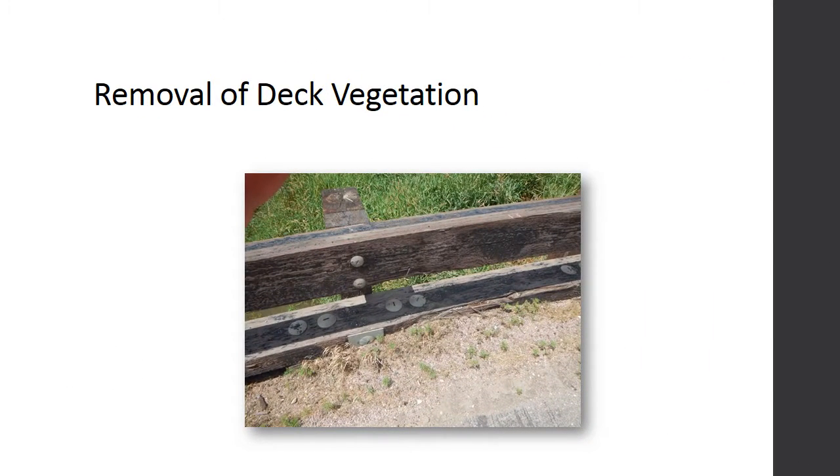Timber decks can be susceptible to vegetation growth as gaps between deck boards are quite common. These gaps fill with dirt and gravel that in turn create an environment in which vegetation can begin to grow. Vegetation growth is a clear indicator that debris has collected and water is being retained within the gaps. As such, the vegetation and debris should be cleared to prevent deterioration of the deck.